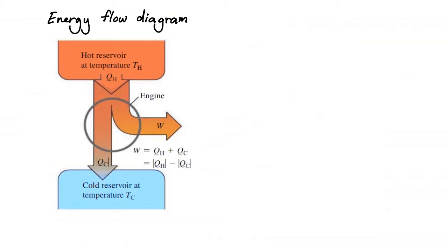So actually, we can see here what we've seen doon sa cyclic process sa ating PV diagram. So this circle here represents yung ating engine. We've seen kanina that heat is introduced doon sa ating working substance through the combustion of our fuel and air mixture. But we've also seen that it has expelled some heat through the exhaust, and then yung area inside our cyclic process kanina sa PV diagram, that is the work done by our heat engine.